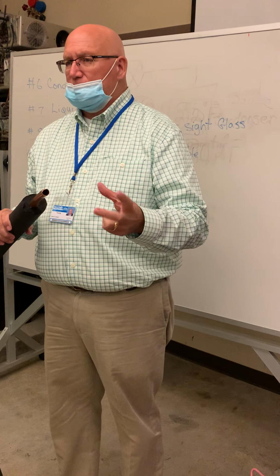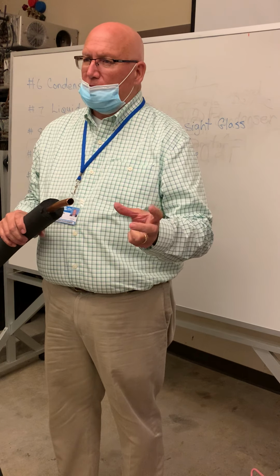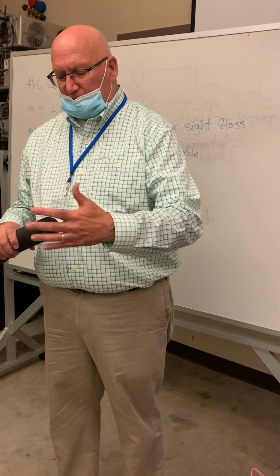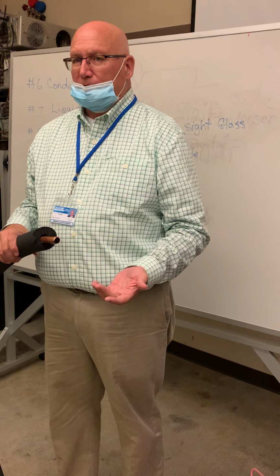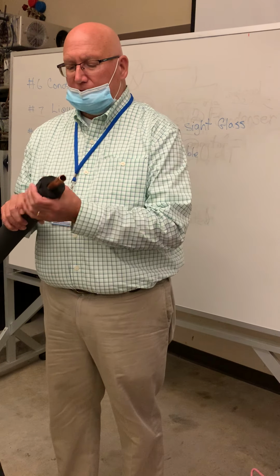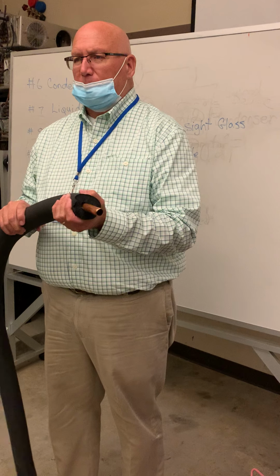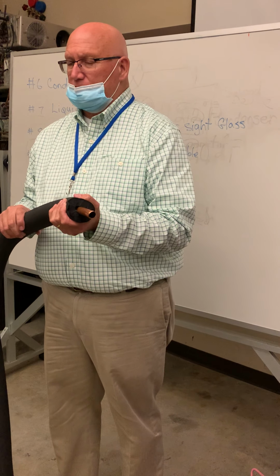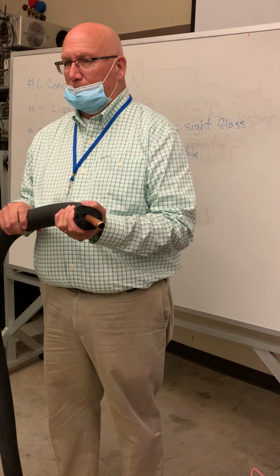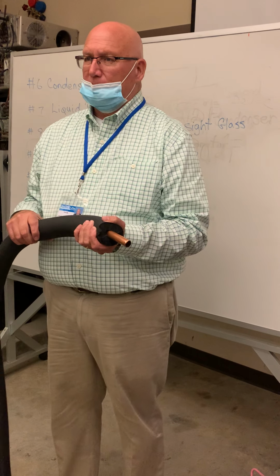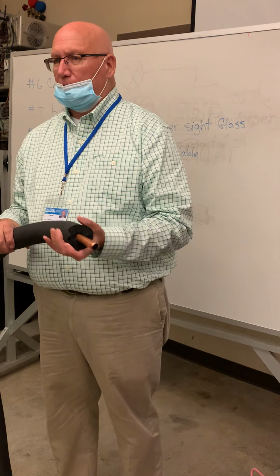That target superheated vapor is anywhere from a sensible temperature of 8 to 12 degrees warmer than that 40 degrees. So as it's traveling back, particularly if it's 75 feet, that's a long way, we have to make sure we keep the temperature stabilized so it does not change states of matter and go back to being a liquid, which would destroy our compressor.